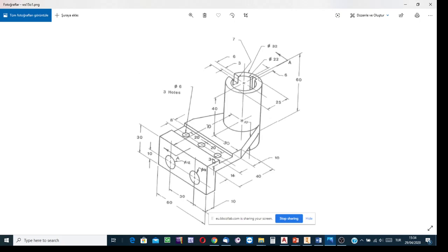Here, while creating the rectangle in AutoCAD, I need to write the XY values for one of the corners and the XY values for the other corner. So relative to this corner, I need to calculate the coordinate of the opposite corner: 40, the distance from here, minus 10 minus 14. Yes, this means the width of this channel is 16.